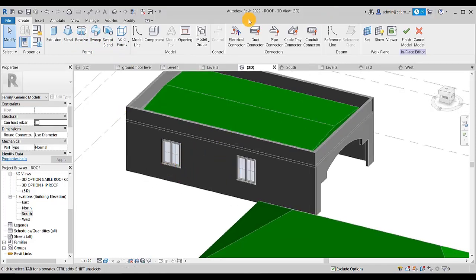So one of the foremost things that you must consider is that when you come to extrude, you must have a work plane. It's very important because I can't draw in space. I have to determine the plane of the wall where I want to do my stuff. So let's start it straight away and see here. So I want to work around this window.